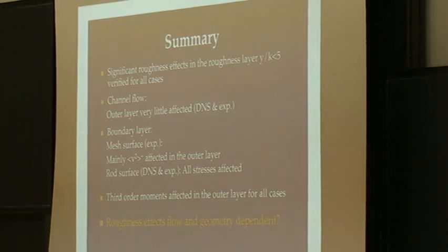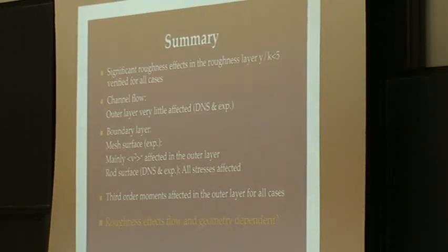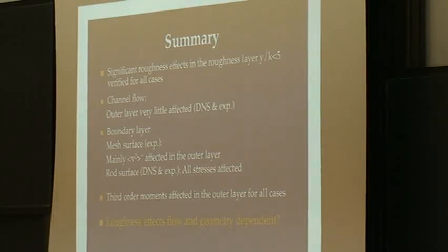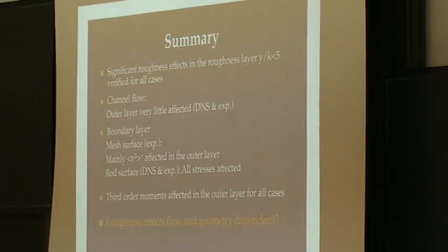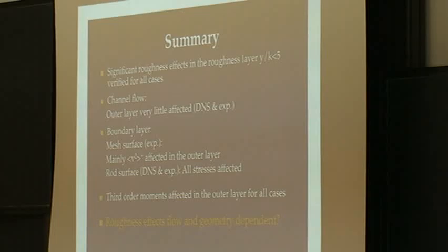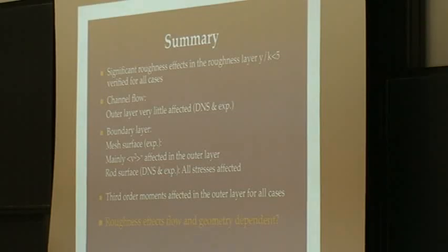Because if you have a boundary layer and it behaves like D-type roughness, which means that it's not the roughness scale as such which is important, but it's the thickness of the boundary layer that is important, then it must imply that there must be a very strong communication across the layer. And I think there's a lot of open questions there.